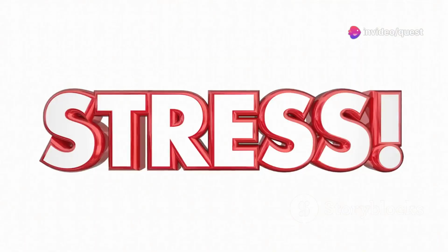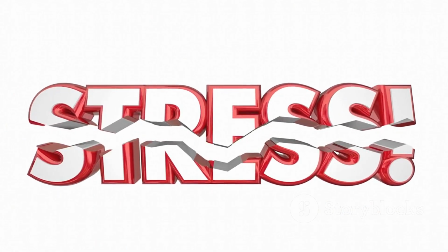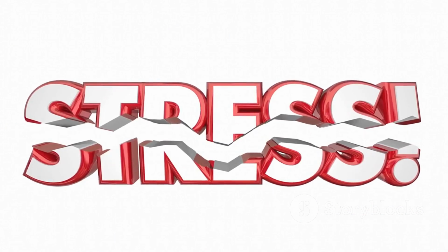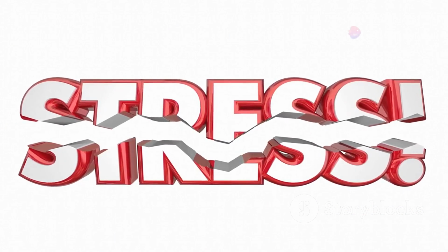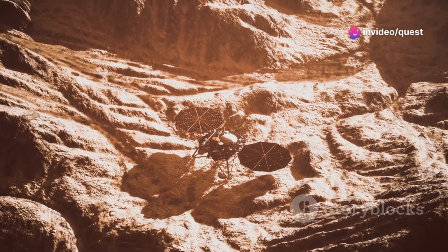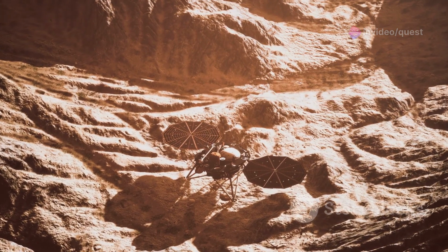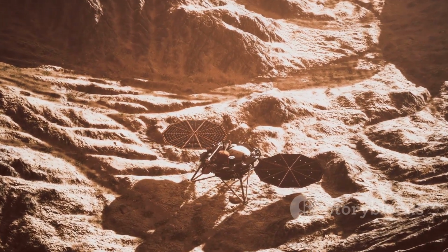Now that we have constructed our Mohr's Circle, let's dive into how to interpret it. Picture the circle as a map, guiding us through the stress landscape of a material. Each point on the circle corresponds to a plane within the material, and the coordinates of that point reveal the normal and shear stresses acting on that plane. The circle's center, for instance, represents the average of the principal stresses. It's the point of equilibrium where the stresses balance out.